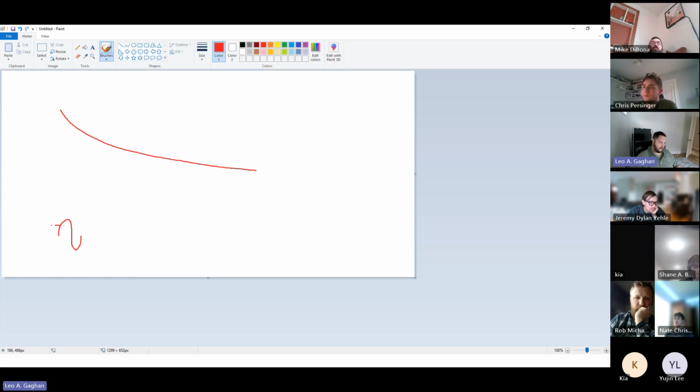You've got your RMS. Your peak is going to be 1.414 times your RMS, and then you've got your DC offset, which at a max is always going to be 2 times peak. That's the worst case scenario.